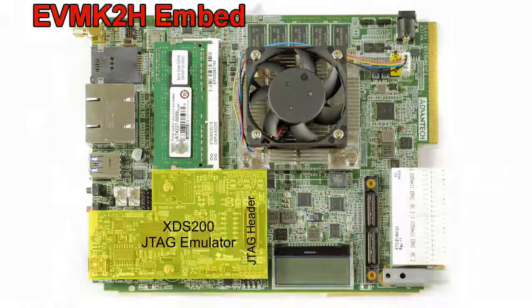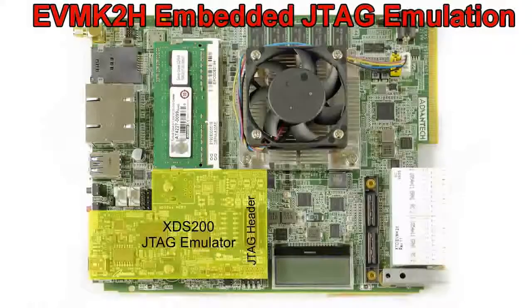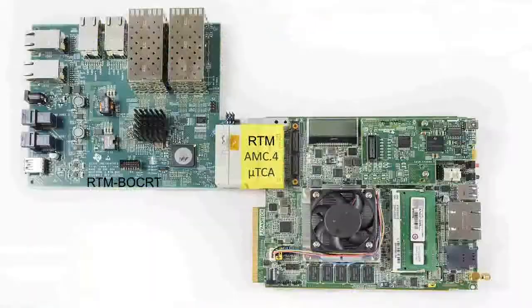The EVMK2H comes equipped with the XTS200 emulator daughter card. Use the supplied USB cable to connect the emulator directly to a PC. A 60-pin JTAG emulation header is also provided for use with any existing high-performance emulator.